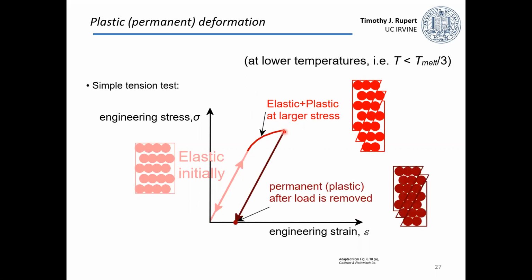Okay, and this is just, again, showing those individual steps. So one thing we might care about in this type of load that I do, so this loading, you get plasticity, and then we unload back to 0 stress, is there's some residual strain that's left over, or a plastic strain. If you want to think about it, this is the amount that my sample has permanently elongated.